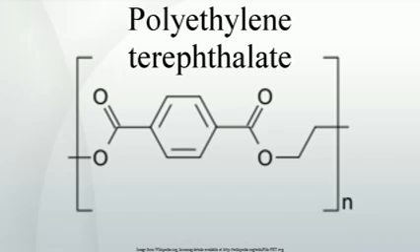Bottle processing equipment. There are two basic molding methods for PET bottles, one-step and two-step. In two-step molding, two separate machines are used. The first machine injection molds the preform, which resembles a test tube, with the bottle cap threads already molded into place. The body of the tube is significantly thicker, as it will be inflated into its final shape in the second step using stretch blow molding. In the second step, the preforms are heated rapidly and then inflated against a two-part mold to form them into the final shape of the bottle.